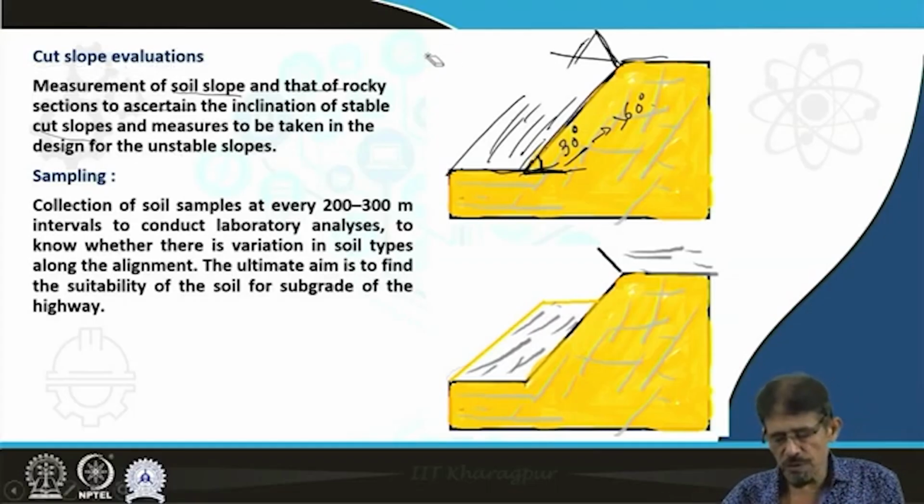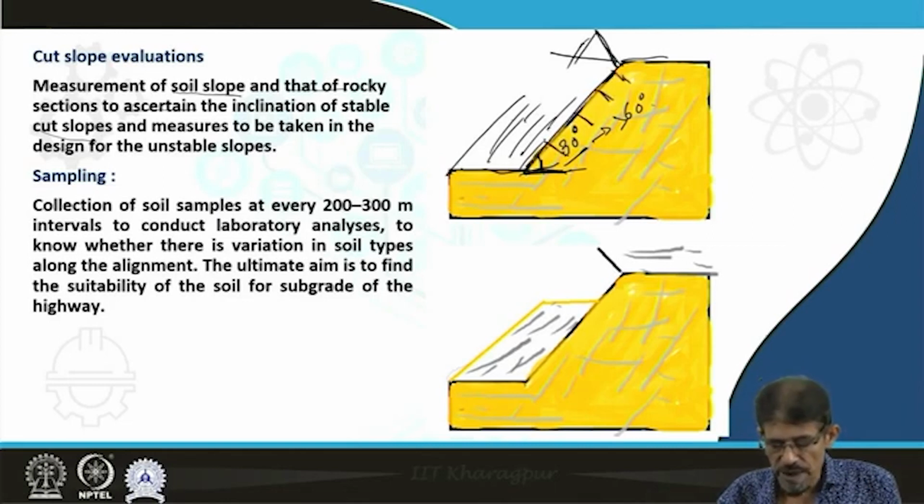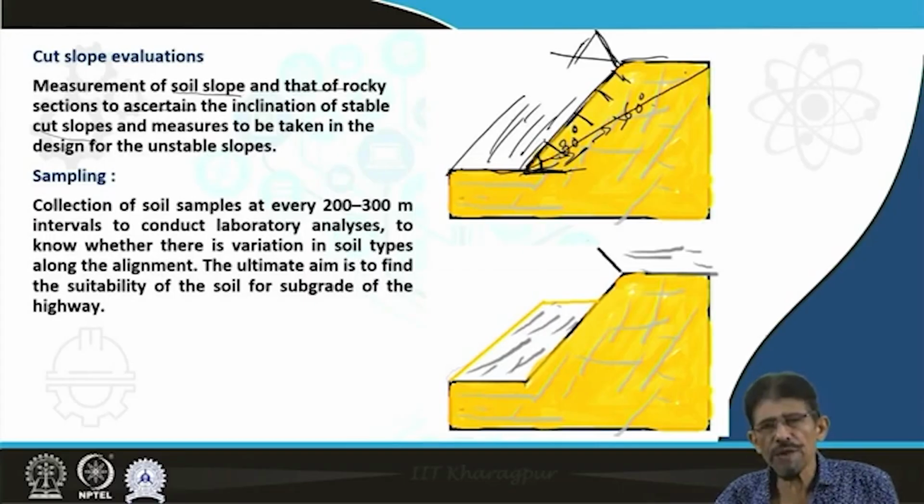If such slopes are not permissible, then we go for treatment, placing some steel nails, rock bolts in case of rocks and others to stabilize the slope. We cannot reduce the angle of inclination very low. A low slope is automatically stable. But when we put a low slope, it means we are going to encroach on more area for road construction. That is not justified socially.